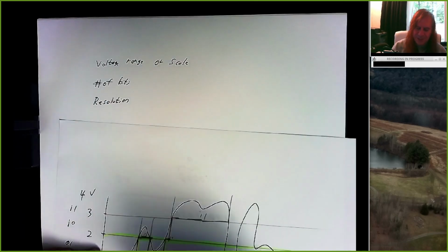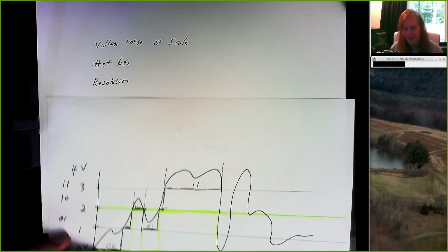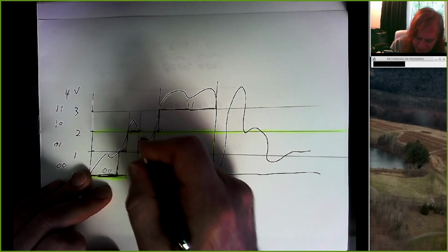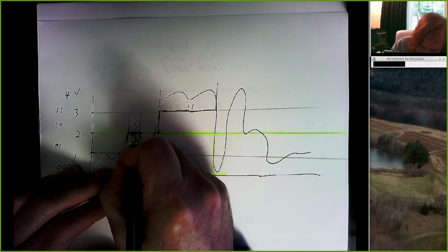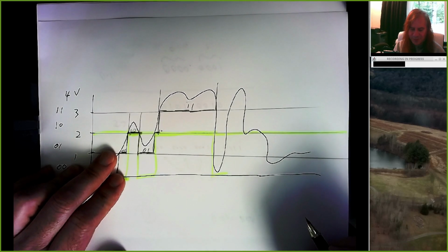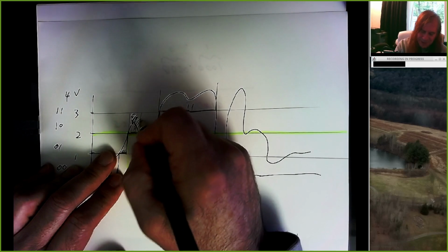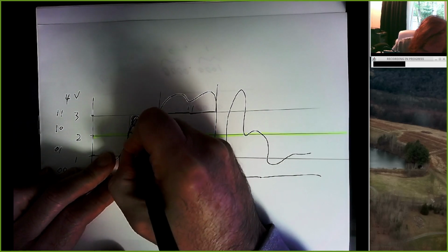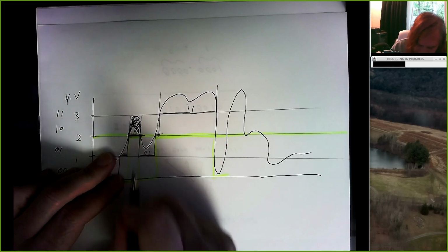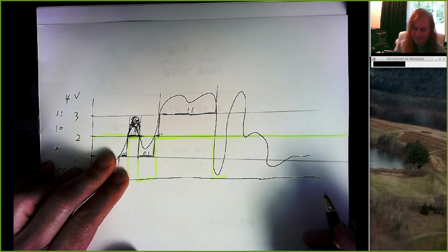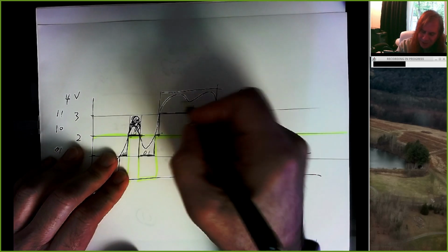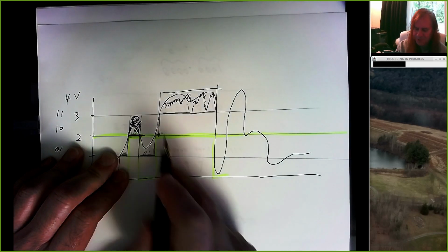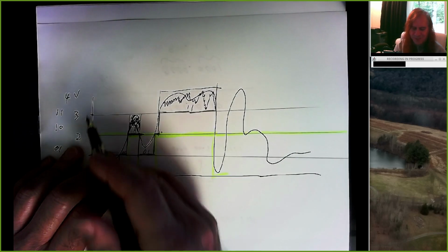There's a pretty simple relationship between these 3 values. For example, if I use 2 bits to digitize, or convert this waveform into a binary representation, and I say right here my voltage level was binary 1, 0, well, if my waveform was anywhere in here, I would store it as a 1, 0. It doesn't matter if it looks like this, or went all the way up here, or wiggled around, or was perfectly flat. I'm going to code it as a 1, 0. Everything up here I'm going to code as a 1, 1, whether it looks like this or like this. With all this interesting stuff going on, all of that would just get coded as a 1, 1, because it's between 3 volts and 4 volts.